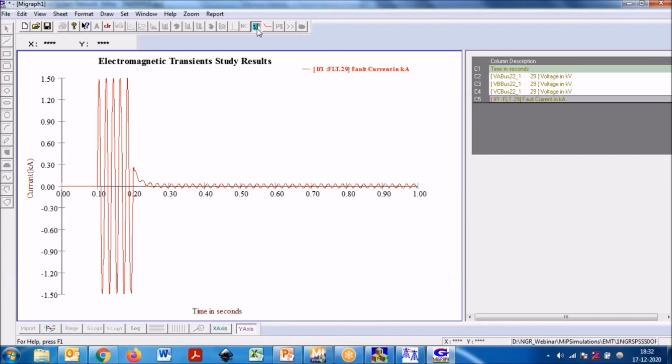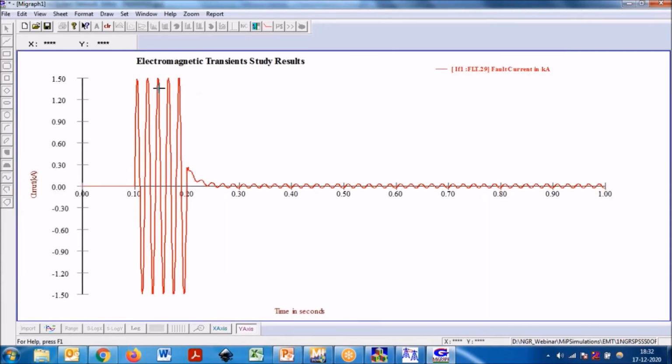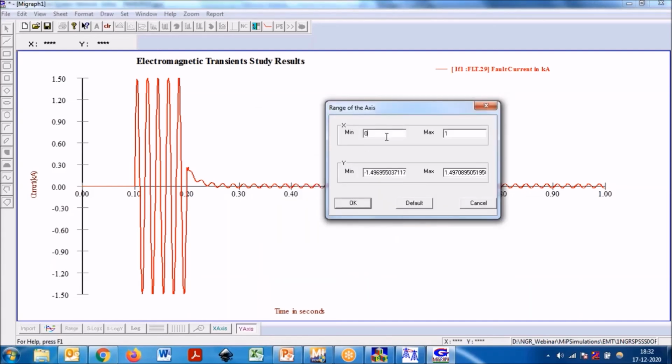Okay. So this is at 50% fault location, and this is our fault current. This is like a primary fault current during the source feeding. Then once the switching has happened, this is what we call a secondary arc current. Generally, this one you can zoom in.